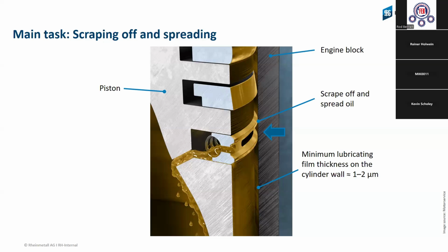Then the oil scraper ring will scrape the oil, but it cannot send it back to the oil pan, because the drainage is blocked. This is also important when you open an engine: you must look, is this drainage open or is it blocked? Is there something wrong? Then it is not a problem of the piston ring, it is a problem in a different part.